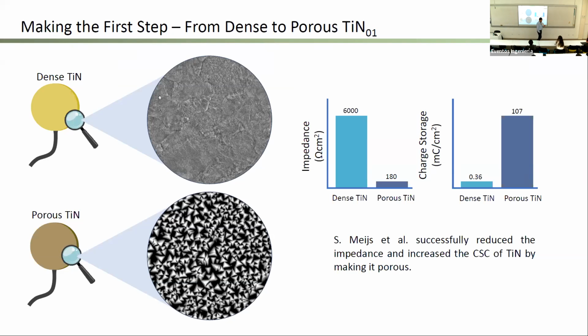It is used in many applications. It's used a lot in tooling. It's used in the biomedical sectors as a protective coating, for example, for scalpel blades. It is also used in the semiconductor industry as a conductive ceramic to isolate metal contacts from the active, let's say, semiconductor material, while acting as a diffusion barrier. In this case, we're using titanium nitride as the main interface or as the starting material for these electrodes.